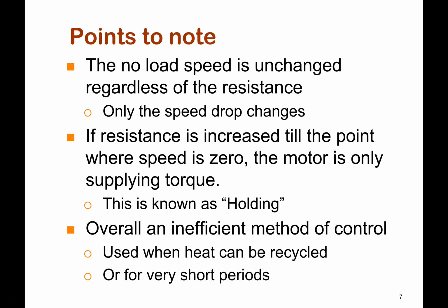We should note here that we already talked about this, the no load speed being unchanged. If the resistance is increased till the point where the speed is 0, the motor is only supplying torque. That is, the motor is actually supplying a torque, but there's no speed associated with it. So this is known as holding, because it will hold the load at that position.